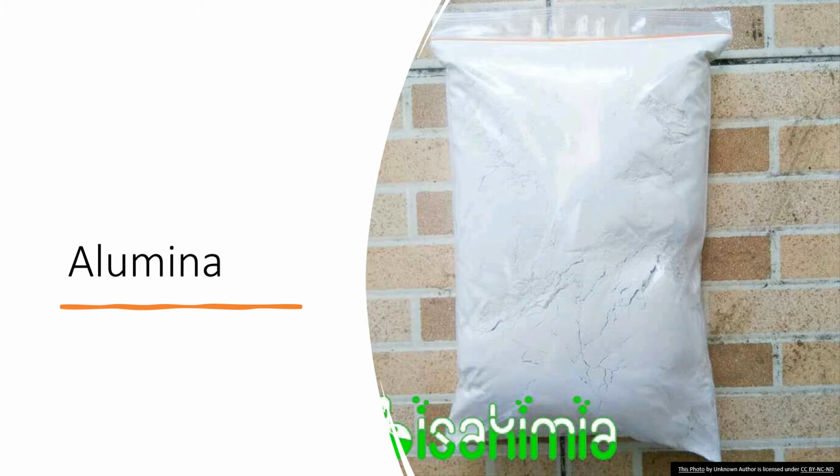Alumina produced by the Bayer process is quite pure, containing only a few hundredths of 1% of iron and silicon. The major impurity, residual soda, is present at levels of 0.2 to 0.6%. In addition to being the primary raw material for producing metallic aluminum, alumina itself is an important chemical. It is used widely in the chemical, refractories, ceramics, and petroleum industries.